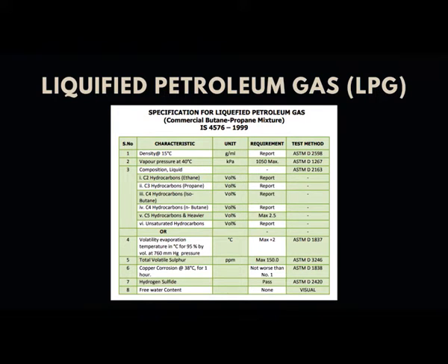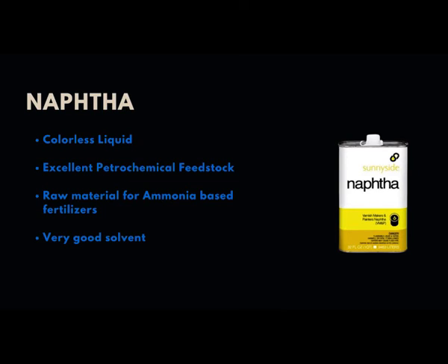If 95% of the LPG sample taken has not evaporated, it means the LPG is heavier and is not going to be effectively used as a fuel, because at the domestic front the LPG is converted from liquid state to vapor state and used as a fuel. Hence this specification is important. Then the hydrogen sulfide presence should be nil. We will move on to the next product.